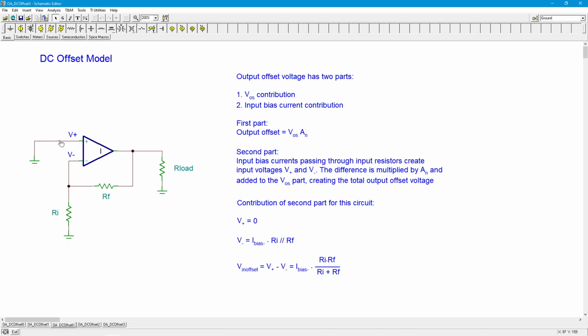So in any case, if you consider for just a moment, if we added a resistor back here, instead of having 0 minus this quantity, there would be a bias current flowing through here. And if it just so happened that the two base currents were the same, and I set the right resistance value here, then we could get a 0 voltage for the differential. In other words, we'll develop a voltage across this resistor, and if they happen to work out to the same number, we have a nice improvement.